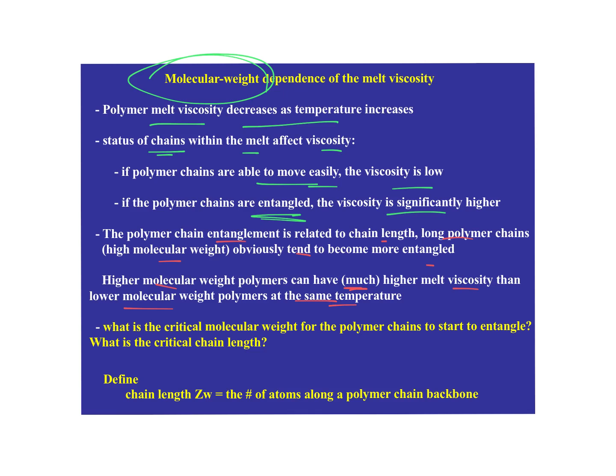All right, so this is one of the limitations that keeps molecular weights low for some particular products. We talked a lot about molecular weight, M sub n, M sub w, polydispersity. But if your molecular weights are very high, you're not going to be able to make a lot of things using tiny channels and tiny gates. I talked about the example of the acetabular cup. You just have a glob, and you put it in the mold, and you squish the glob. It's not delivered to that mold. You have to drop it in the mold. Here we're talking about, can we mold something using tiny little channels, runners, etc., gates and so forth, or not?